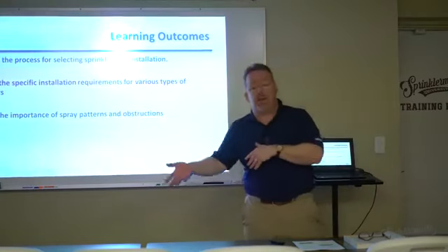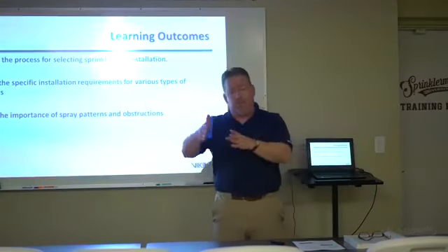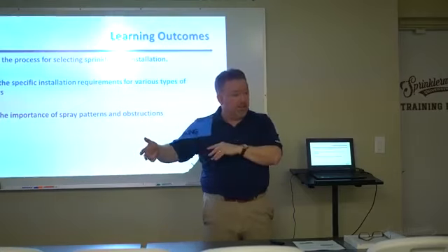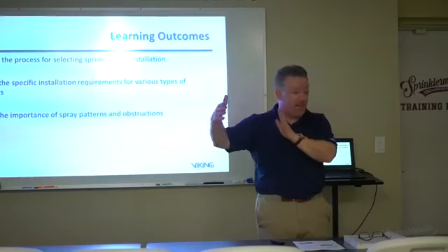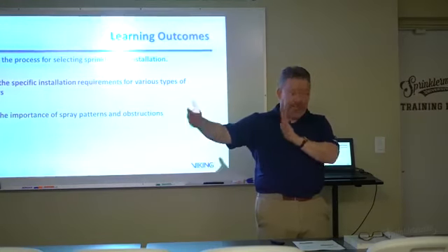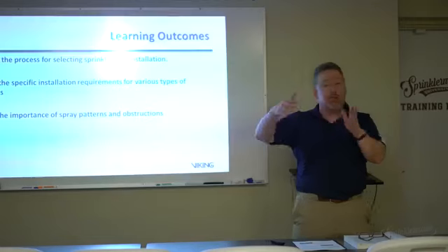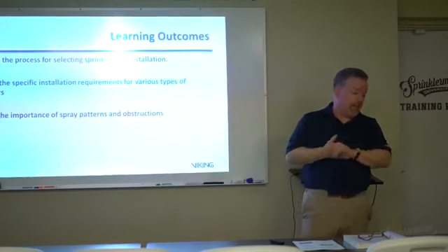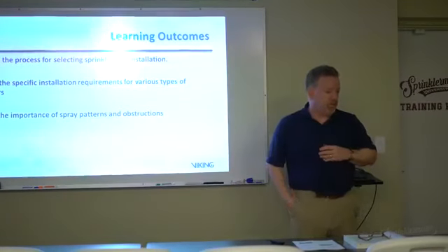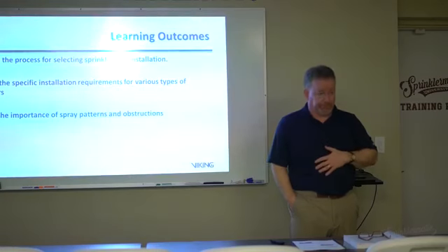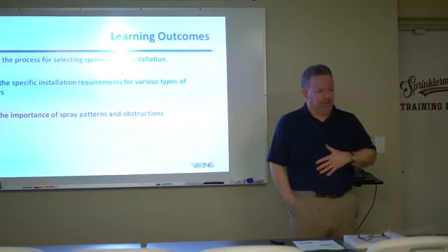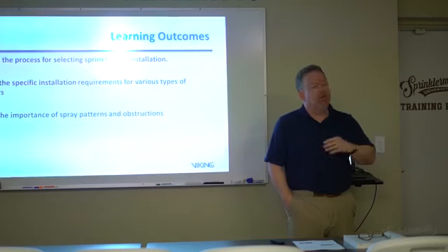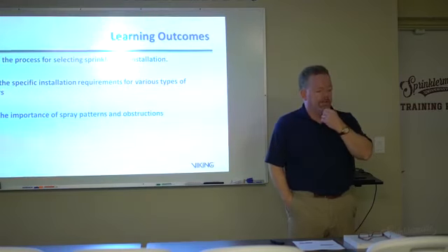Right. Well, if we have an ordinary hazard group 1 occupancy, it's 0.15. Okay, so that has a different water supply requirement. You may not have sized your piping correctly to get that amount of water out, or you may not have the right pressure to get that water out. Okay, it's only built to the light occupancy hazards, not ordinary 2 or 3. So you obviously would have, your water supply would probably be your biggest restriction on the whole system, because they're not going to put a larger main or anything like that if they don't need to.